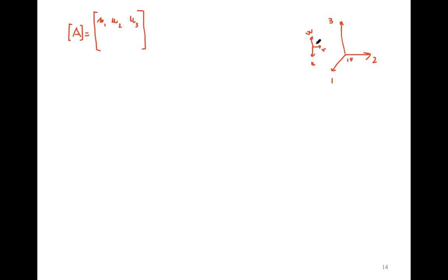And this is the body frame that, as I said, could be considered the OBF, okay? This one will be V1, V2, and V3. The reason why I'm writing this down is that it will also be useful when you want to determine the attitude matrix in terms of quaternions. This matrix enables the mapping from the inertial reference frame to the body frame.